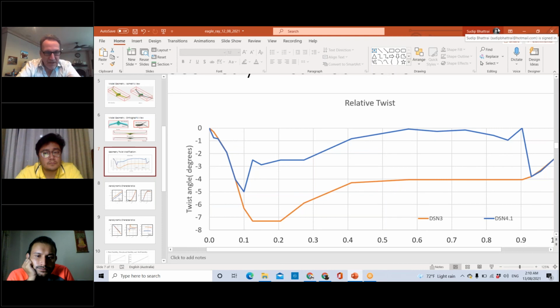It might be fun in X-Plane just to arbitrarily add some more washout. Put like 3 degrees more washout in the tip and have it vanish by 40 or 50% semi-span. Just take the tip and untwist it some and start flying. Of course, it'll be out of trim, really out of trim. You have to retrim it, and then just see if you can help get rid of some of that spin propensity. I'd like to hear if that happens. If you see that, that would be very helpful to know. Okay, yeah, I'll try that. Mm-hmm. Yeah.